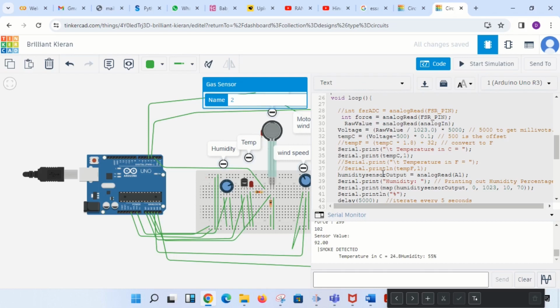So this concept is very simple. Just read the temperature, humidity, and force using analogRead. Within the brackets you have to mention the humidity pin number, the temperature pin, and the force pin. Here the force, pressure data, is stored in a force variable, and this is for humidity. Humidity is stored in one variable. No, sorry, this is for temperature.